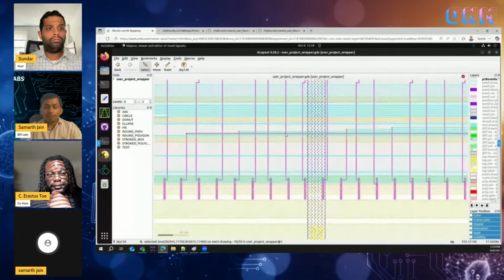So it's a simple CPU with a wishbone interface, which you can connect. Wishbone is a bus, like maybe CAN or AXI. You would have heard these names. Wishbone is a very simple bus which you can use to communicate digitally with your IPs. So there's a master already built into the RISC-V for the wishbone, and there is a slave already built into the NVM IP which we provide. So you can directly interact with the memory mapping available in the datasheet.